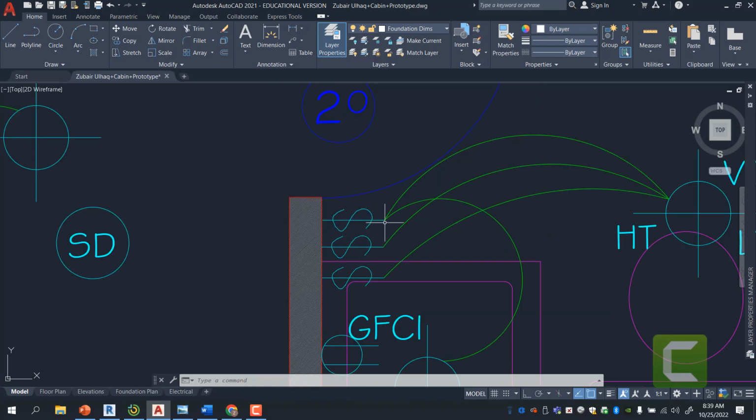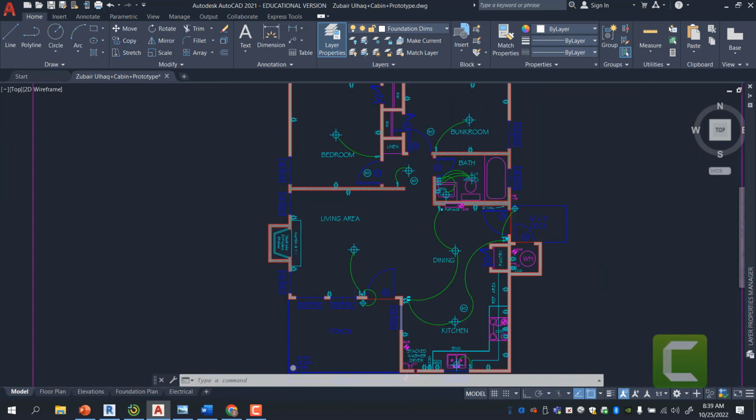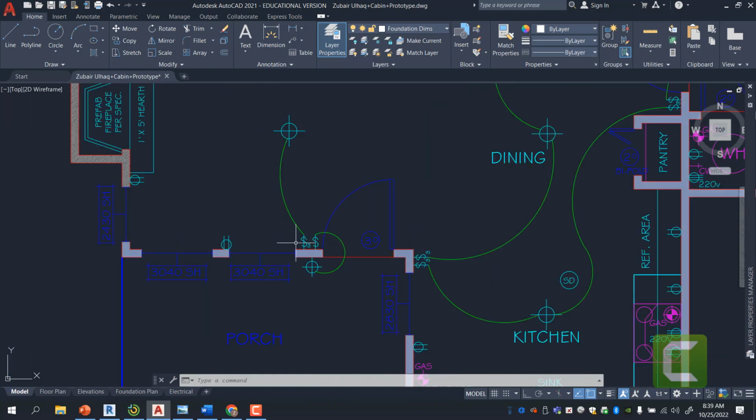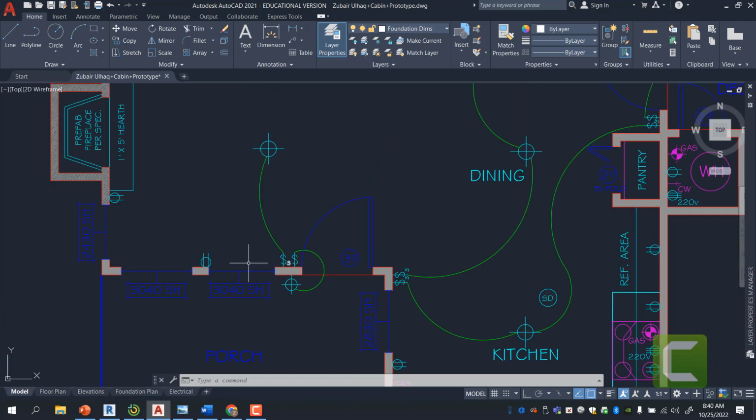Now, you could put S3, which would indicate that this is a three-way switch, and point it to this one fixture. Now, it is being done here on the plan, and there's a reason for this three-way switch being here, because there's not enough space. So you have a switch with 3 switches on there, and then you have an additional switch that controls the light for the outside.